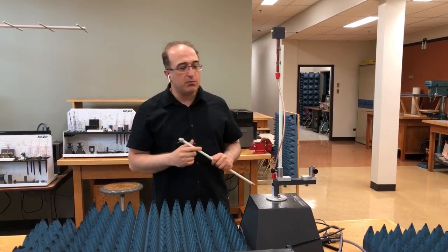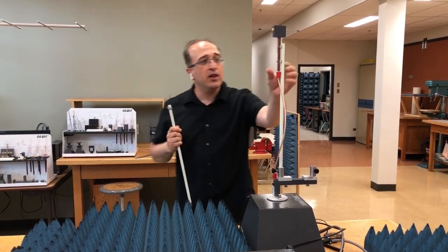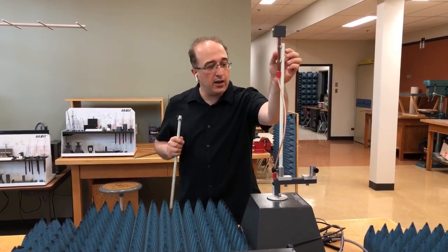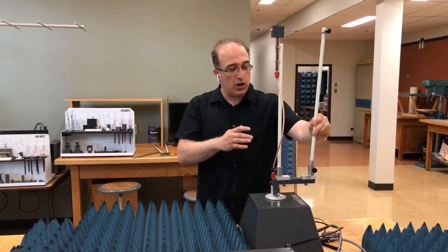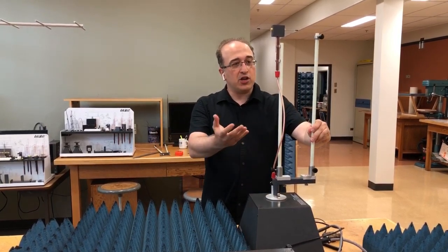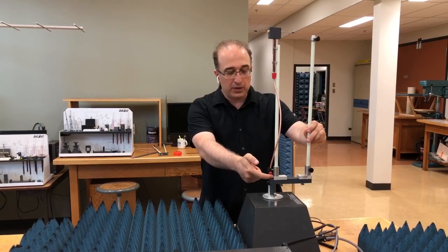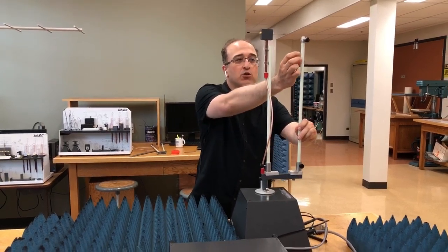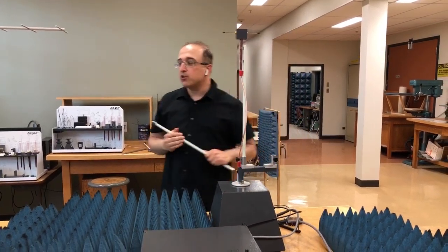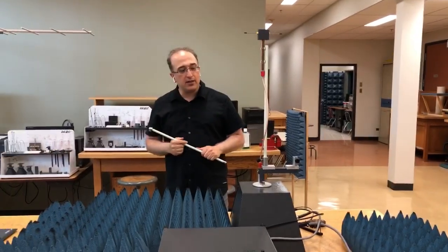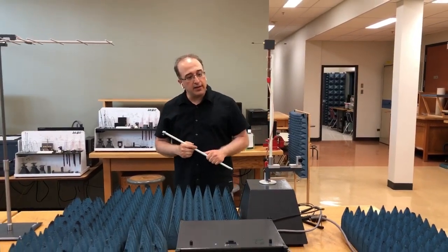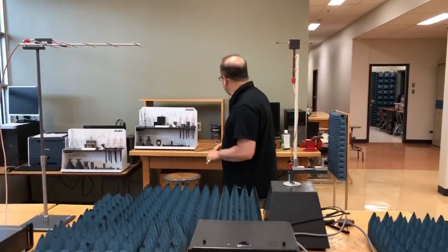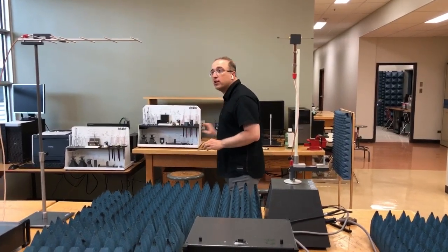Otherwise, the measurement is not going to be accurate. For example, if I take this dipole antenna and I mount it on this rod here, my measurement would be wrong because that would be the axis of rotation, but now your dipole is here. So you need to make sure that the axis of rotation and the dipole is along each other. So that's one thing to keep in mind for accurate measurements.